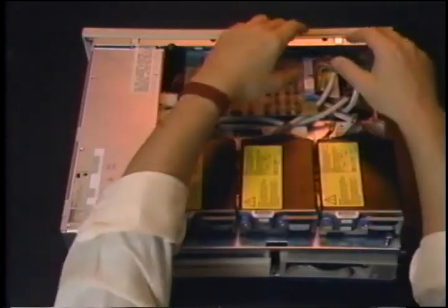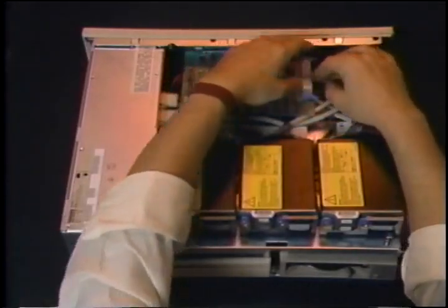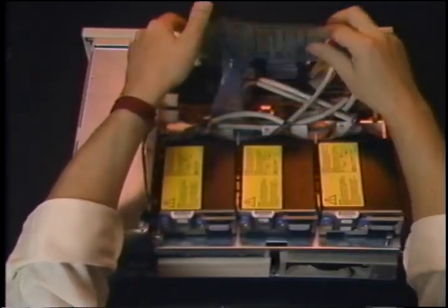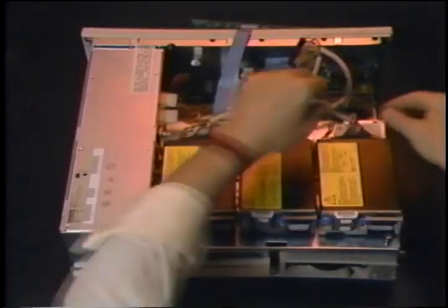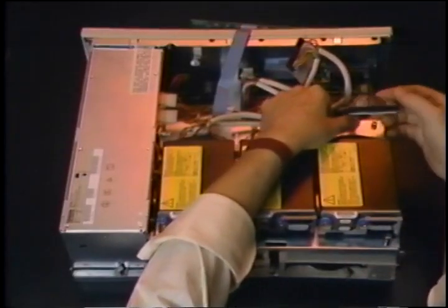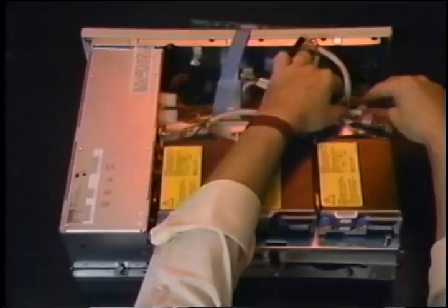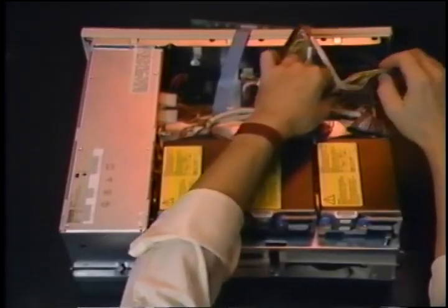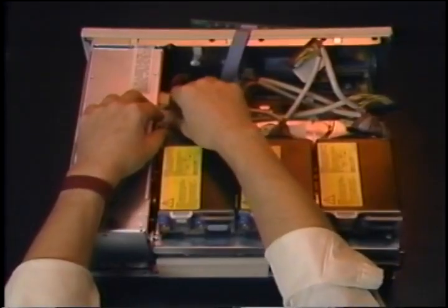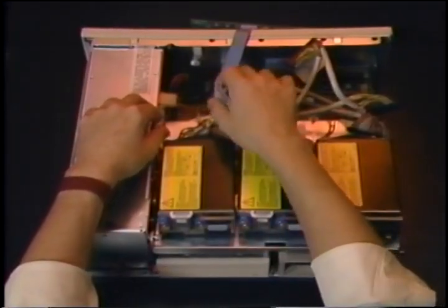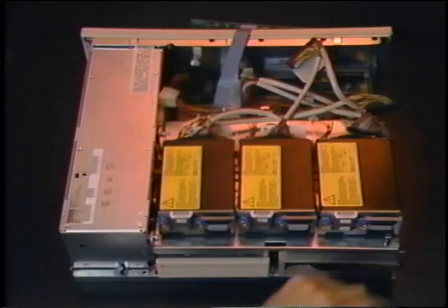Disconnect the SCSI control cable, lift the controller from its standoffs, and let it hang over the back of the system. Disconnect the data cable from RZ0. Disconnect the SCSI B cable from the pop-out on the mass storage controller. Disconnect the front power supply cable to the 3 RZ23s.